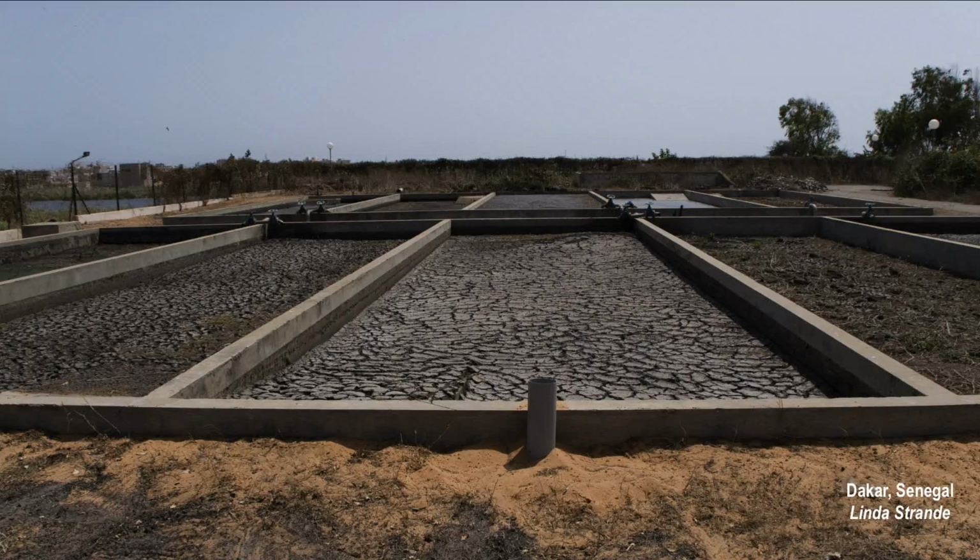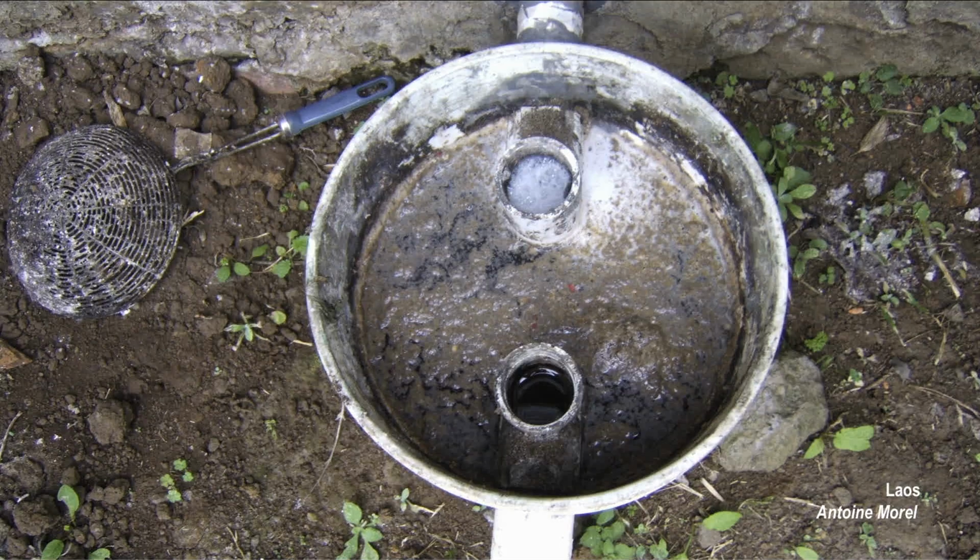In the same way that sludge settles to the bottom of black water, lighter particles will rise to the top. Fats, oils, grease, and surfactants, or FOGS, is the name given to all the frothy scum that floats to the top of a wastewater, particularly gray water. FOGS generally comes from the cooking fat and soaps that are used in the kitchen. FOGS can clog pipes and pumps if it's not removed early in the sanitation chain.